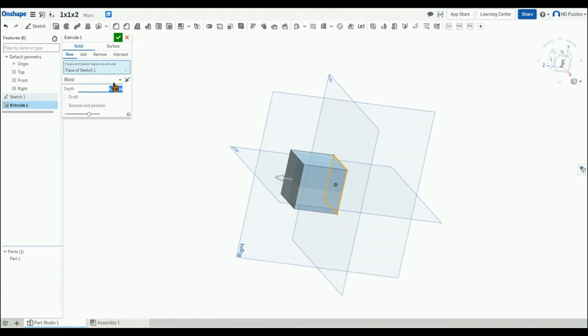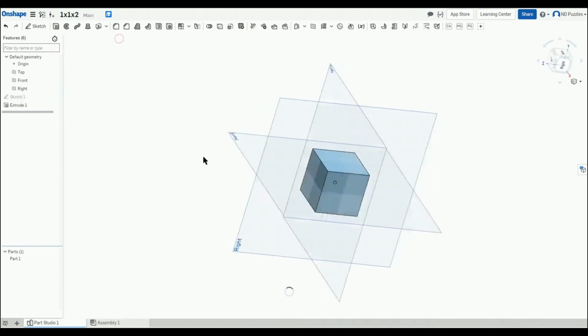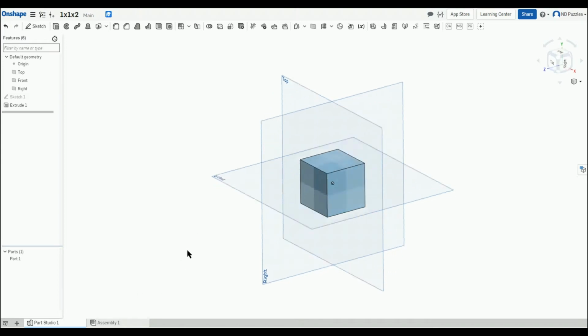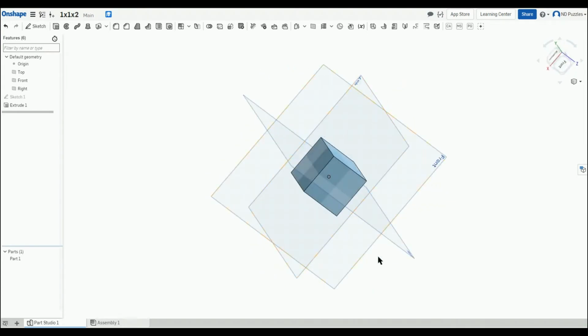Congratulations! You've now got a rectangle. Well, kind of lame. Not exactly what we imagine as a puzzle and not even a 3D solid either. But wait! I'll now show you how to convert this boring rectangle into a 3D solid. To do that, there are basically two features: extrude and revolve. Revolve is used to create rotating solids. If you used this feature on a rectangle, you end up with a cylinder. As we want to go for a cuboid though, we choose the extrude function.